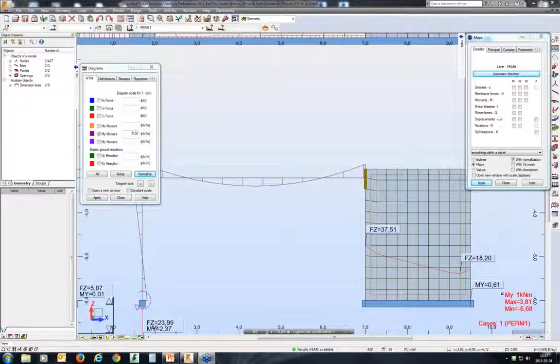If you care only about bending moments, and this is going to be only the thicker part of the slab, just create a panel inside a panel with different thickness. Otherwise, just create the drop panel below the actual raft foundation and then connect these two panels either with rigid links or vertical panels like walls.